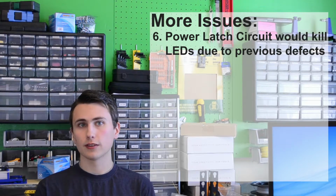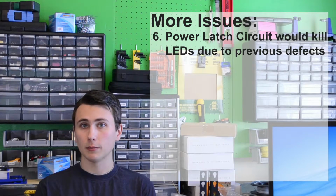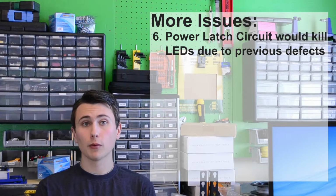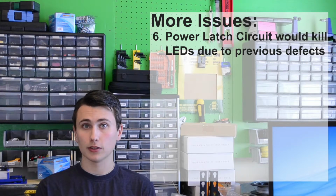These three design issues in combination reminded me of some of the things that I already knew, but in my haste to move forward with the project, I ignored my past experience and plowed forward anyways. Let me just reiterate those lessons, so hopefully I won't forget this time. 1. Always design your hardware, so if the hardware or software does the worst possible thing, nothing will be damaged in the circuit.